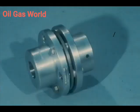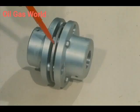The third type of flexible coupling that we will cover in this training module is the disc coupling. This coupling does not require any lubrication whatsoever, since there is no real metal-to-metal friction. The advantages of this type of coupling are built into this shim pack, or disc, as it is called. This pack of thin, flexible metal plates allows the coupling to move in various directions without seriously affecting its operation.